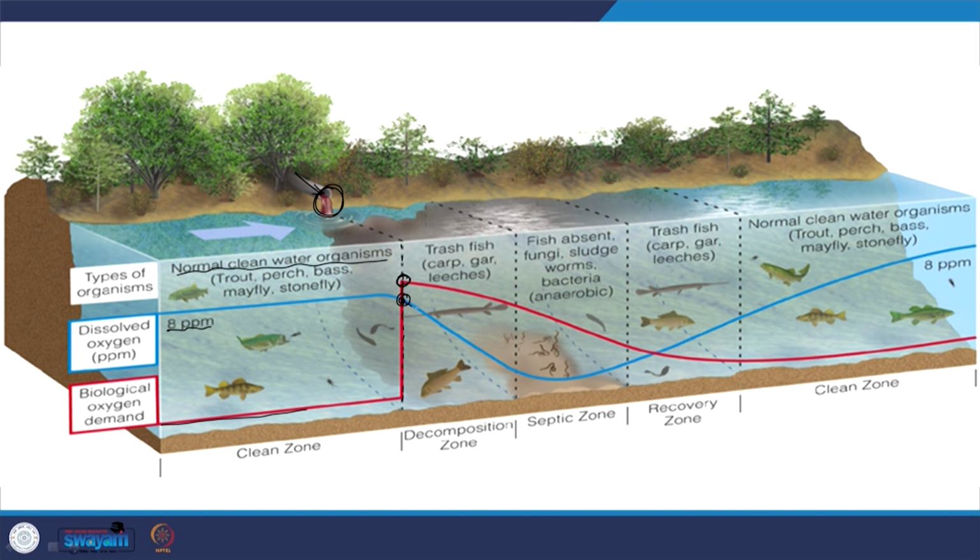But now what is going to happen, the DO is going to start decreasing. Why is that? Because the microbes are going to degrade this organic content in the presence of oxygen. So, the organic content is going to be decreased. We looked at this graph earlier, or even here, dL by d theta is equal to minus kL, let us say. So, L at theta is equal to L naught into e power minus k theta. So, you see exponential decay, that is what you see out here.